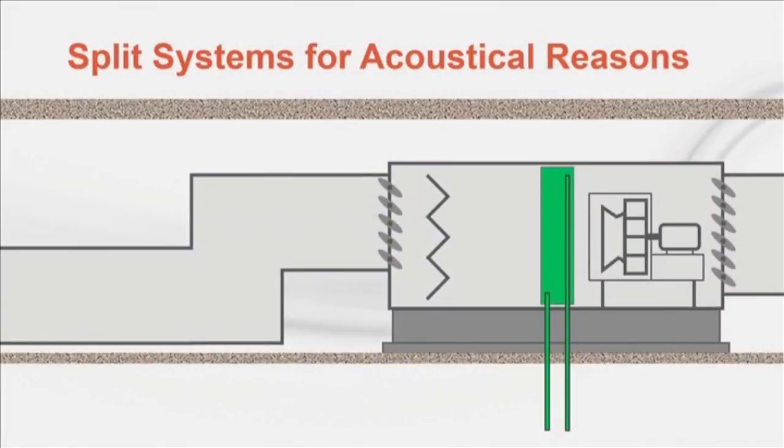Separating compressors and fans allows the compressors to be placed either indoors or in a bunker to attenuate the radiated sound. One example is to place an air-cooled condenser coil inside an air handling unit designed with quiet fans and sound attenuation to meet the project sound goals. This will reduce unwanted noise, but it will increase system complexity and first cost.